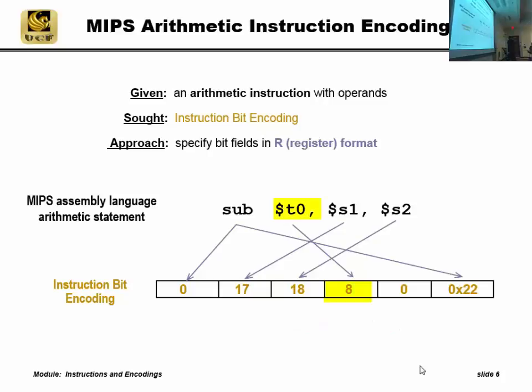So if I look inside that field, you can put a logic analyzer on it, and then you'll see those bits. How do you see the bits electrically? What does it mean? There's a voltage, right? If it's a 0, it's 0 volts. You put a voltmeter there, it's going to read 0, and if it's a 1, it's 1.2 volts or 2.8 volts or whatever your processor's high voltage is. That's it. Sub, actually we're going to see, is represented as the combination of 2 different fields, and they don't do that to be complicated. It's actually to make it fast. Anytime you have a 0 here, you have to look in this field to see what the operation is, but it means that it's an arithmetic instruction. When it's a 0, we'll get back to that.